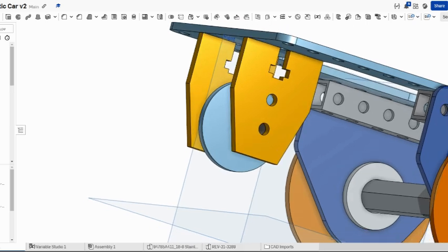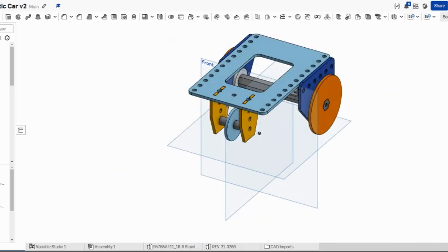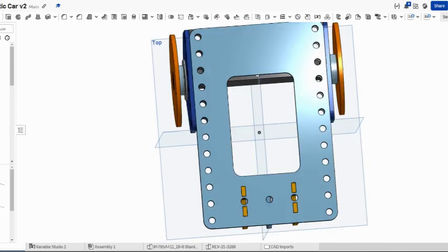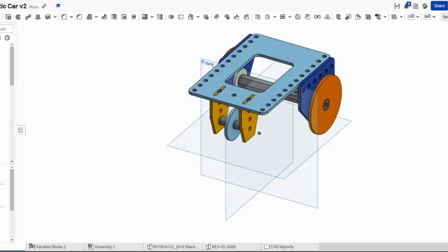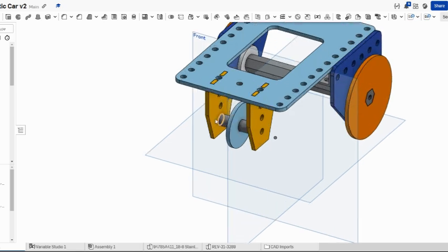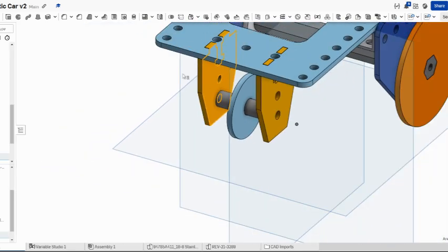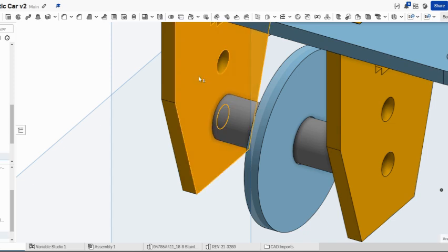There is a view cube in the top corner, so you can select different faces to be able to rotate it. So we want to click that corner so that we've got the front, right, and top. And we're going to zoom in here, and we'll select that face. If you've accidentally clicked multiple things, just zoom out, click some blank space, and then you can click the face to select only it.